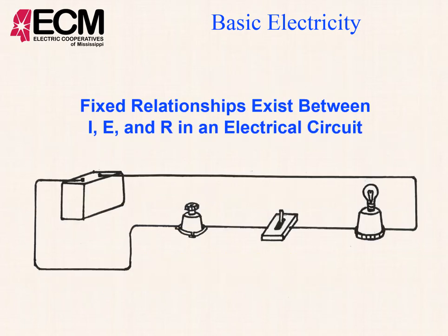The question is on our power lines, when our neutral is down, or maybe our neutral's down, and we know that's our return path. There's always current flow on our neutrals. How do our lights continue to stay on? And basically it's because of all those ground wires, pole grounds that you put on the pole, and all those ground rods that you put down. That completes the path.